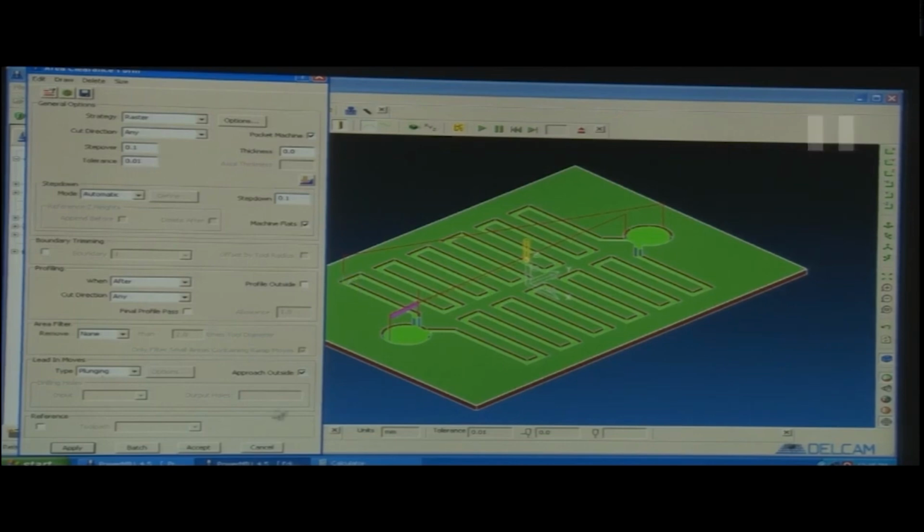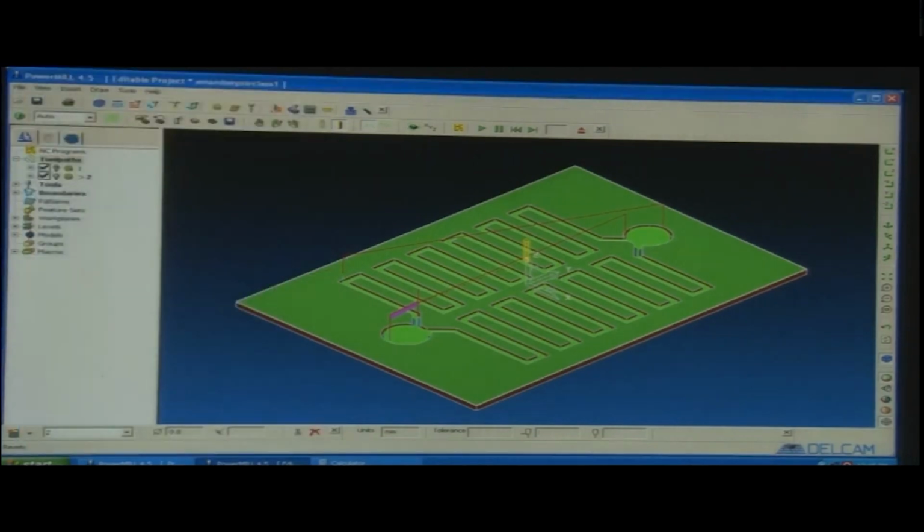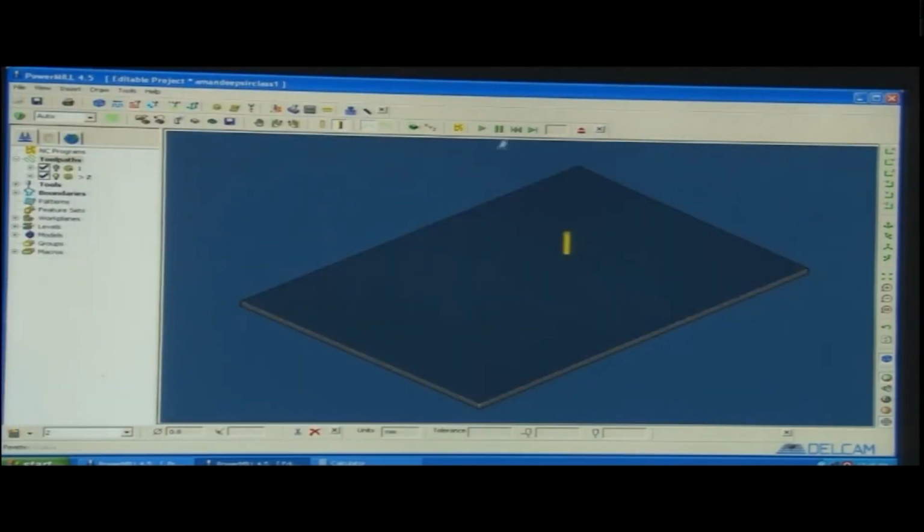This is important to see, because in case the operator or the coder who is trying to put the values manually might forget to put some minus sign, or forget to put some value properly, there might be some accident. So, it is important to see how the rapid movement is happening. Rapid movement always has to happen outside the workpiece area. So, that is important to see.